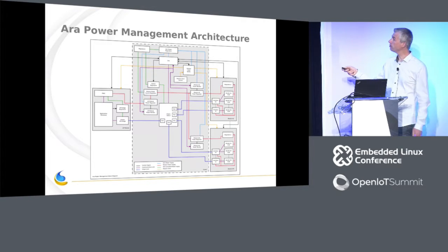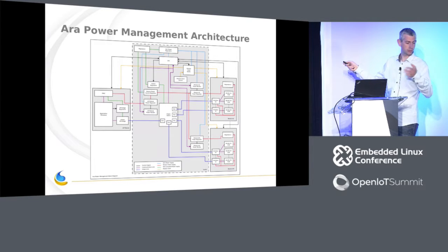okay? This Greybus operation depends on what we want to do, but for instance, for power on, power off, we will send a power on, power off operation to the SVC. We will also send an operation to the module to do some software maintenance first. But the idea is that there is a runtime PM callback invoked on the AP. This is translated into one or more dedicated Greybus operations that are sent to the given module and to the SVC.